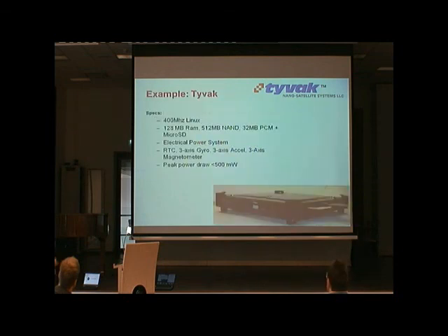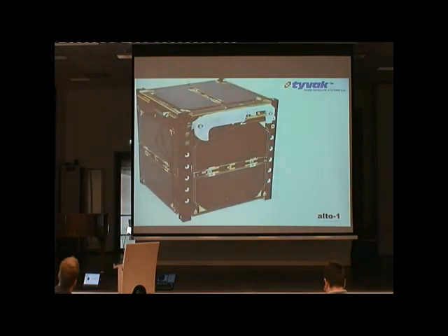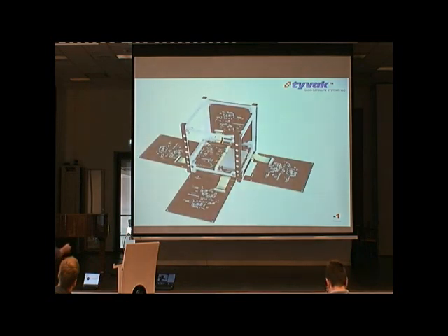Everything is integrated. For example, the entire EPS, the power system, is integrated into the boards of your solar panels. So what you can have is an entire satellite actually for your payload. You go to the shop, you build or buy this platform, and you have almost the entire 1 liter of volume for your payload. So you can put anything you like in here.